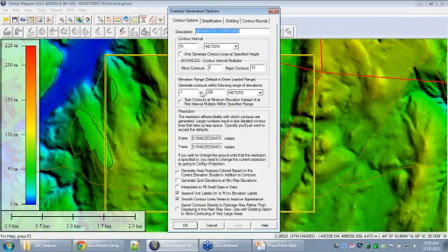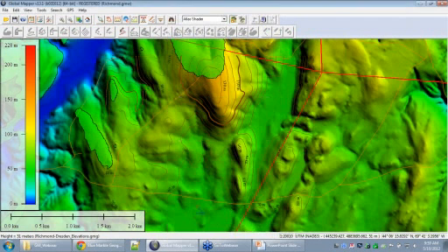And as well, we can crop the elevations if we want to only see specific contour ranges, and as well set the resolution of our analysis. And that's really used to speed up the process if you're doing a very large area. So we'll OK that contour generation.